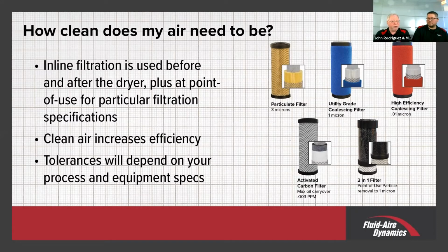The charcoal filter could be changed as much as once a quarter, and maybe even more often than that if there's a lot of oil in the line. That's why you have those other filters previous to that, so there isn't that much oil. It all depends on what you're doing, but as I said, my standard would be a 3 micron prior to a refrigerated dryer and a 0.01 micron after it. In general terms, that gives you clean enough air to run almost any manufacturing facility.